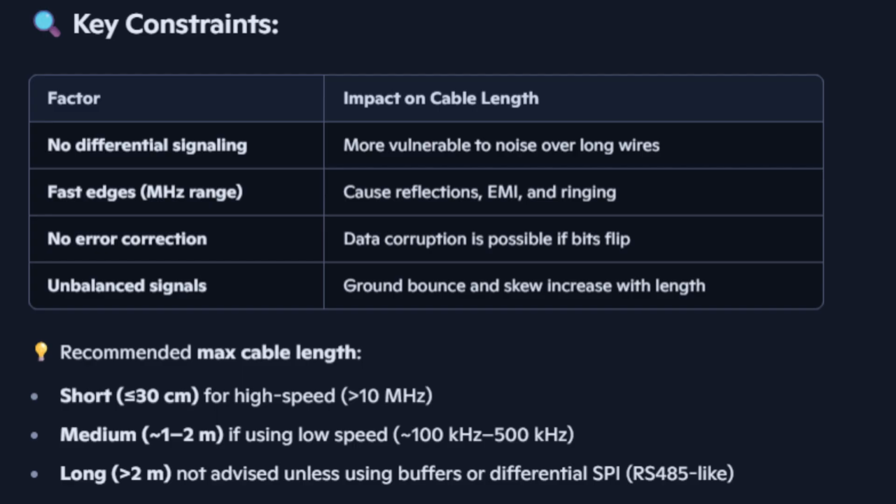Anything beyond 2 meters is really asking for trouble, unless you use special SPI bus buffer chips or convert the signals to something more robust like RS-485. Trying to run fast SPI over long wires is like trying to have a clear whispered conversation across a noisy stadium. The message just gets lost. Okay, so keep it short, especially at high speeds.